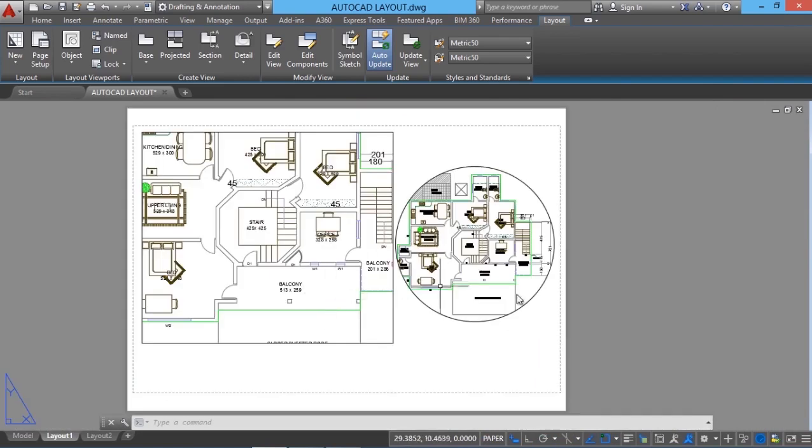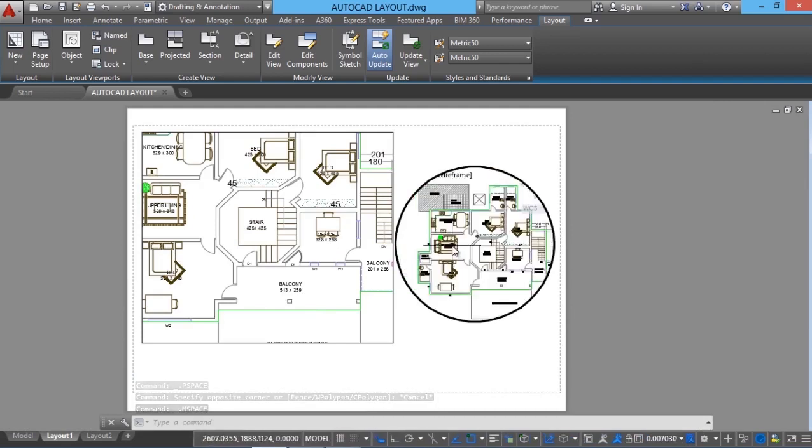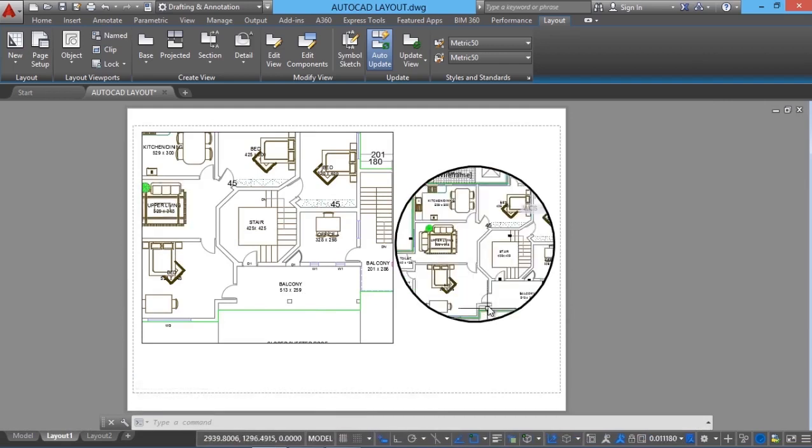viewport. So similarly, I would like to activate this viewport. So just double click it. I can zoom in and zoom out. So likewise, you can activate a viewport by double clicking. Now when you double click outside the viewport, as I told you before, you are in the paper space and you will also get a triangular icon which is called a paper space icon.